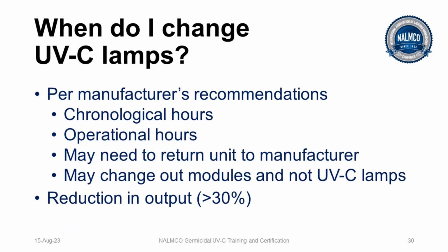Now, when do I change UVC lamps? Well, again, it's per manufacturer's instructions or recommendations. It may be chronological hours, may be operational or arced hours, or a combination of the two. In some cases, you can directly change out the lamp. In some cases, you may need to return the entire unit to the manufacturer.